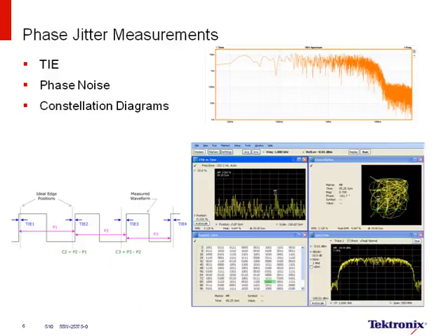So that's step one. The second part is you have to make sure that you know what the TJ peak-to-peak max spec is. The reason is because making a TJ measurement without knowledge of what the peak-to-peak or the max spec is for TJ is irrelevant. Why? The receiver could have things like equalization. Okay?